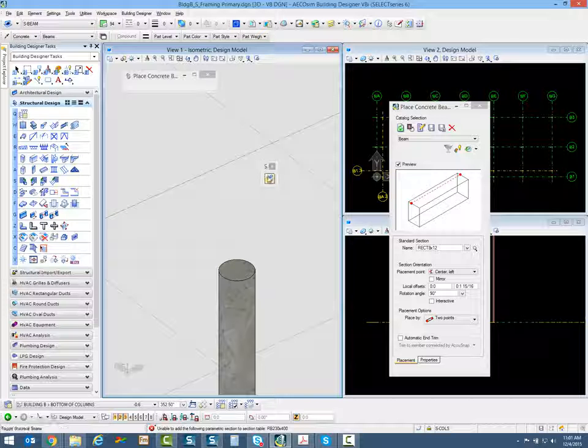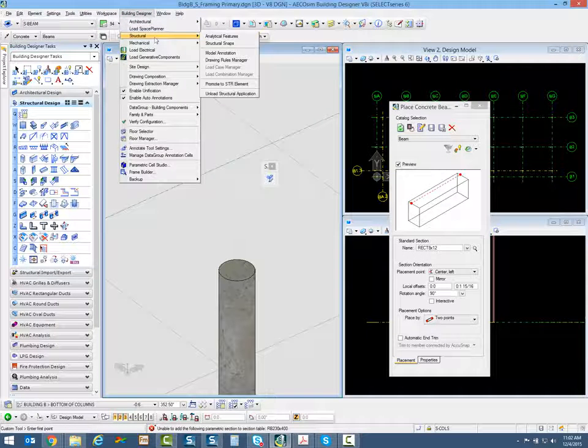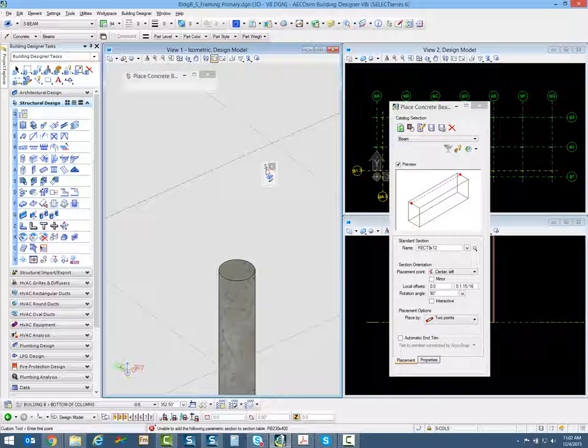And you can turn that off and on with this. This is just a toggle. You see if I click on it, I see that it's off up here now, so I could turn it off and on from up here. But every now and then, I don't want to use the structural snap for certain things that I'm modeling, so I can turn it off as I need. But when you have it on, you need to be on the key point snap mode. You'll see that it snaps on to that structural snap.